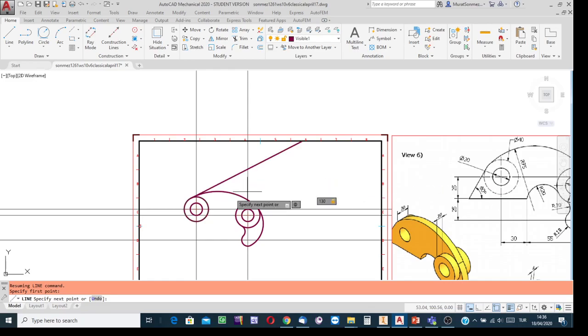It makes 240 degrees. I calculated the inclination angle of the line with respect to the horizontal reference that passes through the tangent point, as measured in the counterclockwise direction. I determine it as equal to 240. Do not write 60 into this box, write 240 and then press enter.